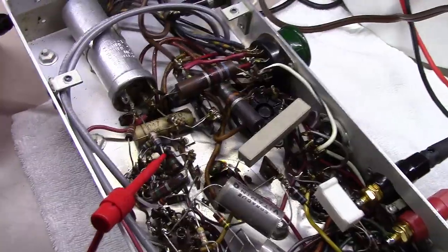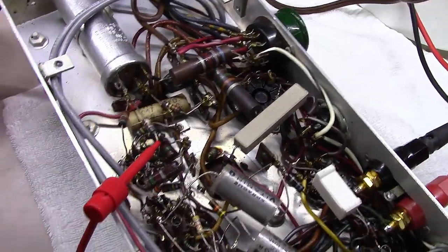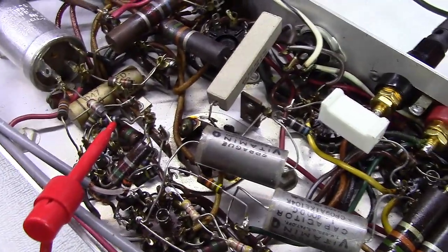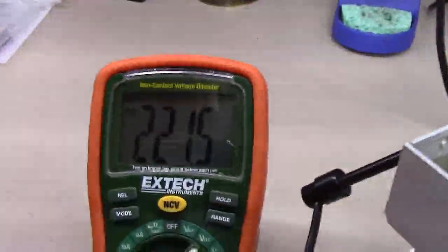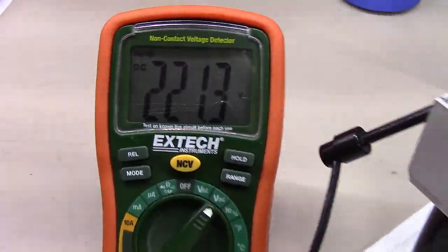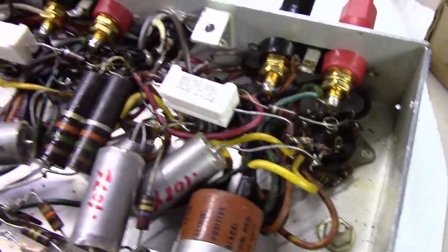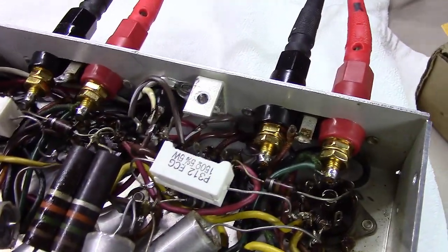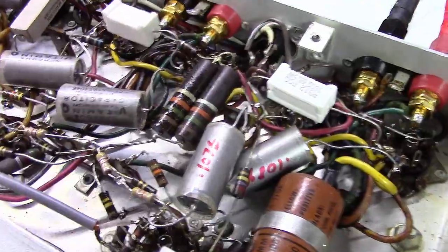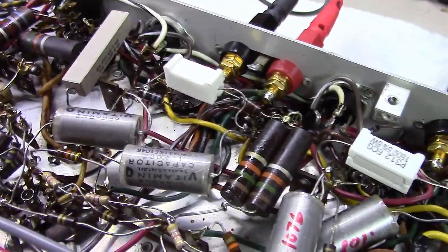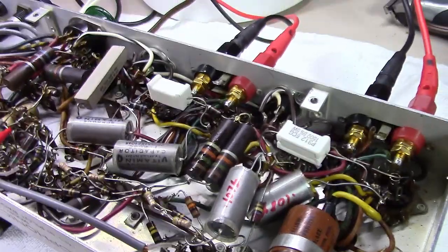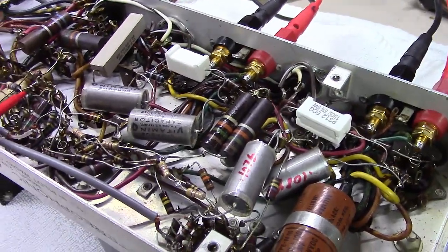Alright, I picked another place inside of this amplifier, and this is on the plates of the 12AX7, 12AU7 tubes. If you'll notice, they're running at 221 volts. Not nearly as hot as these power output tubes, the 6BQ5s or EL84s in the outputs here. So as you can see, throughout an amplifier chassis, there are many different voltages running around and different potentials per se. So let's jump to a schematic. I'll show you a little more.